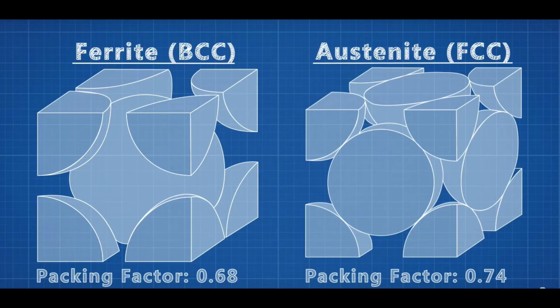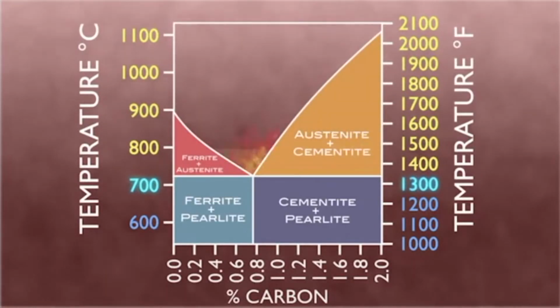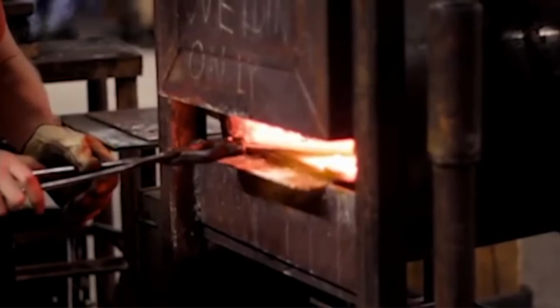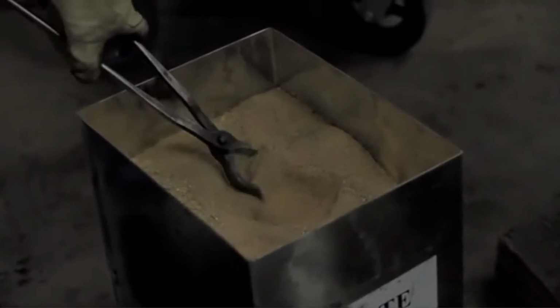In order to produce desired properties, heat treatment is an important process. The first step is austenitization. The steel rods are placed into a salt bath or a furnace in a range of 1150 to 1290 Celsius. This is the austenitization temperature for typical high-speed steel, including M42, and the temperature is held for 5 to 6 minutes.